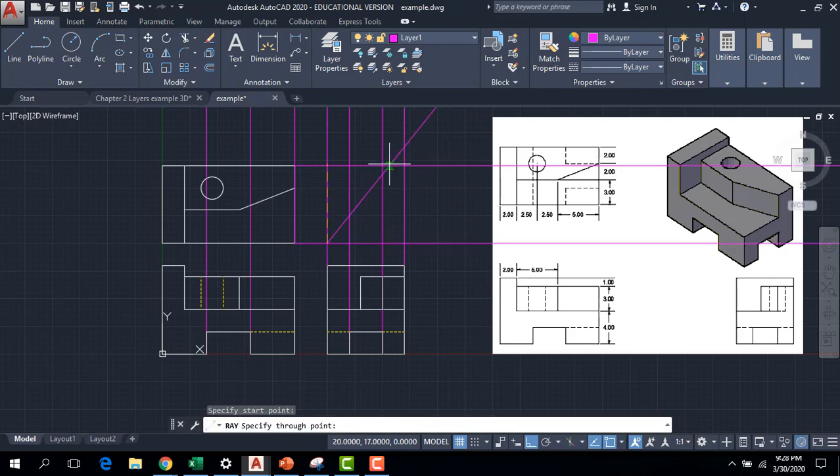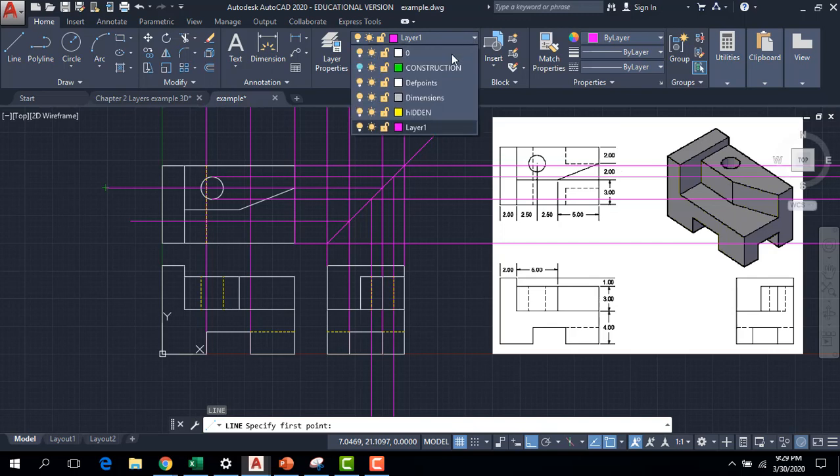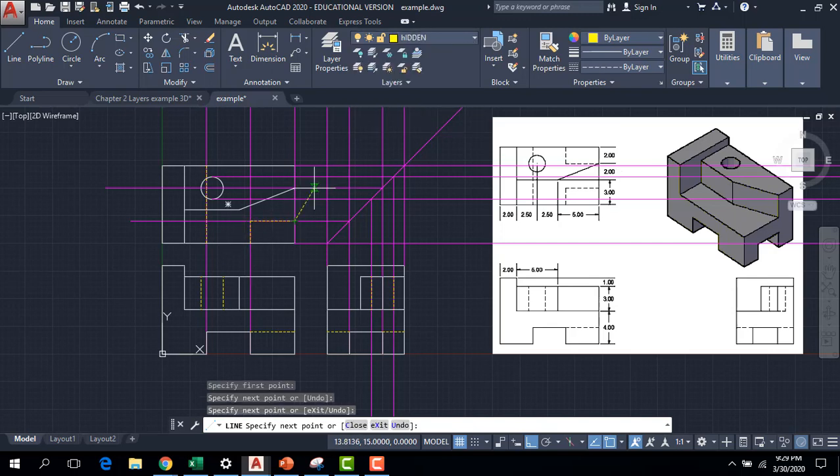And if drawing in XY coordinates will help, here's that miter line again. So we need to add in the last of our hidden lines here. So there's where our circle is going to go. So we can add the side of that cylinder over here with those miter lines. And then we also need to see where that cutout is with respect to the top. So there's the miter lines to show where that cutout is at the top, and we are almost there.